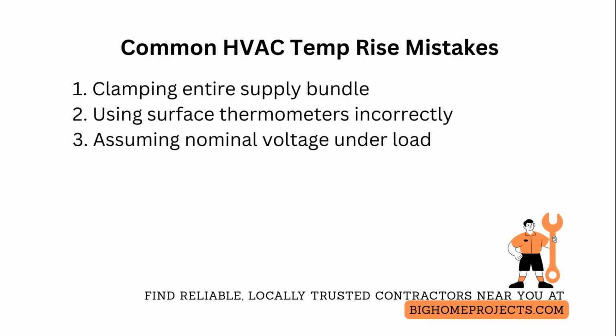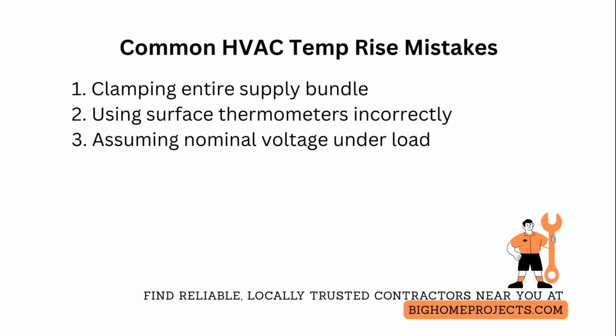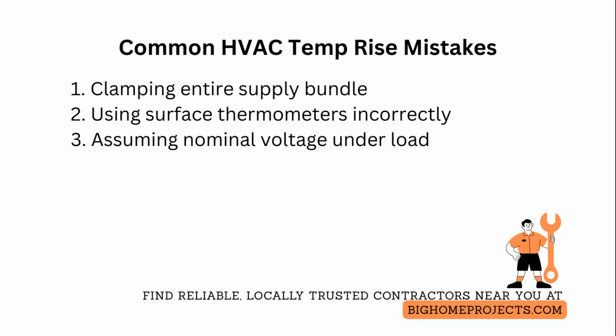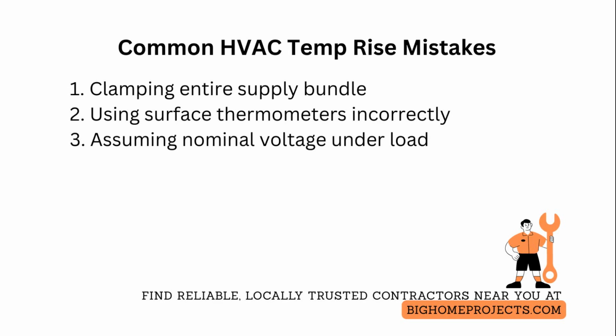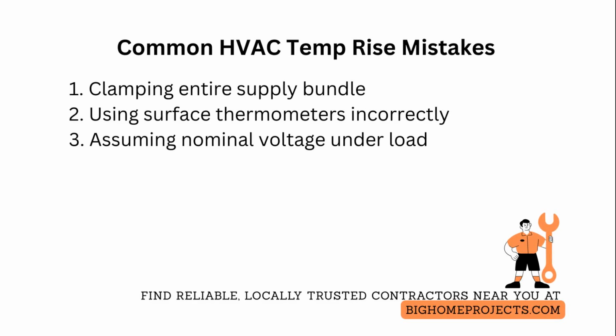One of the next frequent errors is using open air thermometers or surface probes instead of true airstream thermocouples, producing wrong temperature rise and thus wrong CFM. Fix this by using a calibrated insertion thermocouple or vane thermometer placed directly in the airflow and averaging multiple samples.